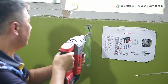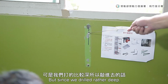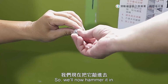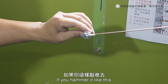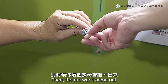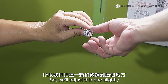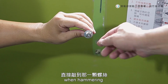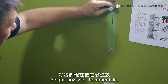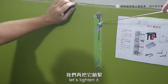Good. This indicates dust inside, but since we drilled rather deep, the dust will be trapped inside, so we'll now hammer it in. If you hammer it like this, you might flatten this area. Then the nut won't come out, so we'll adjust this one slightly to avoid hitting the screw directly when hammering. We'll hammer the nut instead. Alright, now we'll hammer it in. After that, let's tighten it.